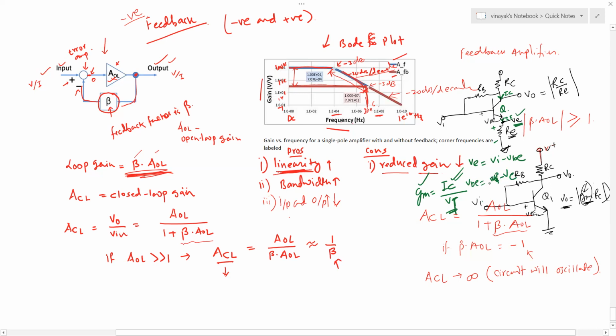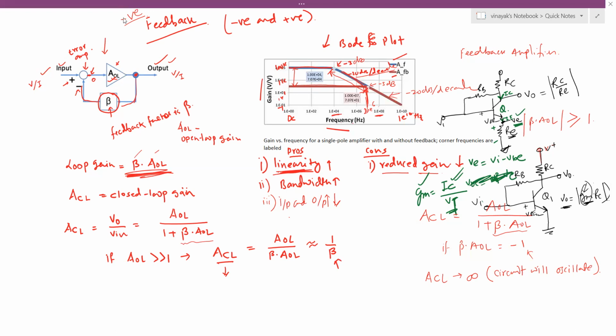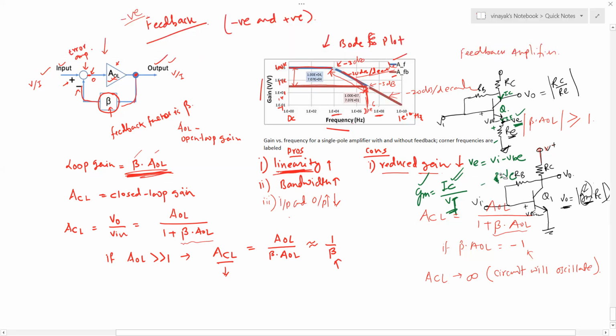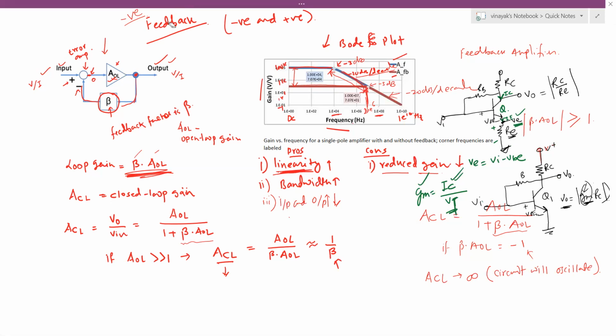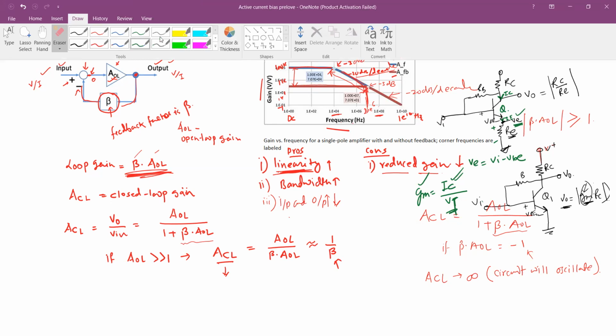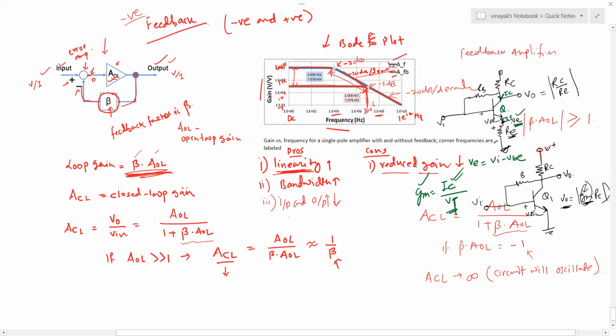Okay, so, oh, just a second here. I think we are making a mistake in explaining things. So the voltage drop across RE will change, the current IE will change because the IC changes. And then IE, we know that is IB plus IC. And therefore, IB is equal to IE minus IC, right? So IB will change then.